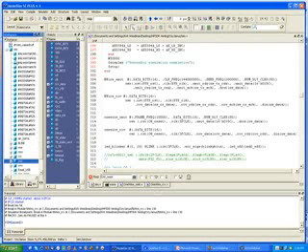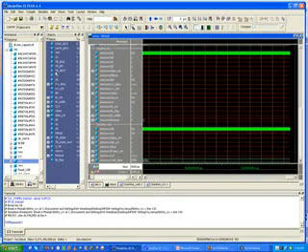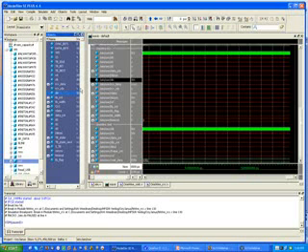So within there, and this is in ModelSim that I'm doing this, you can go in your hierarchy, you can click on the particular instantiation like OWR here for the one-wire receive, and here you get a list of all these internal signals and variables that you're using. Okay, so what I did was, in the wave file, I just clicked on them and then dragged them over and added them in here earlier, so you can list the signals that you want to see.